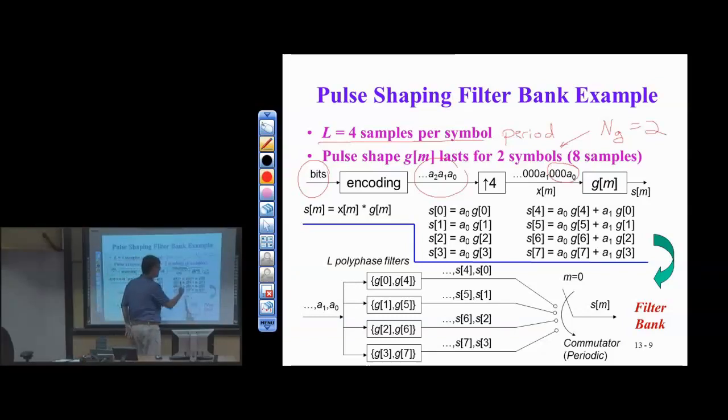and if I look at this, I go, I got artifacts, I want to do an FIR filter on this. So that's great, but now if I look at the calculations involved, the FIR filter is going to do a lot of math with 3 zeros. We're going to multiply the FIR coefficients against these 3 zeros. I'm wasting my time. Why am I multiplying by 0? So there's a more efficient approach, which is a pulse shaping filter bank, and it gets rid of these multiplies by zeros. It's just incredibly efficient. It's a win-win. You don't lose any precision in the calculations, and you remove all the unnecessary multiplication by 0.